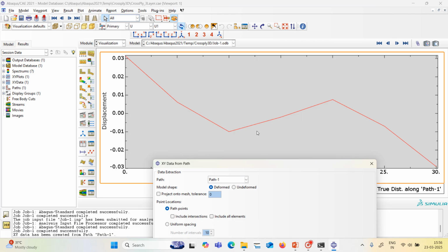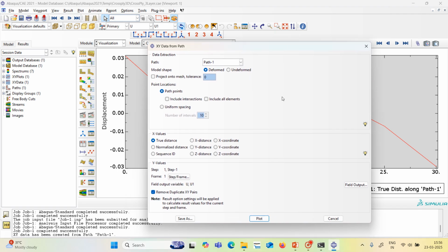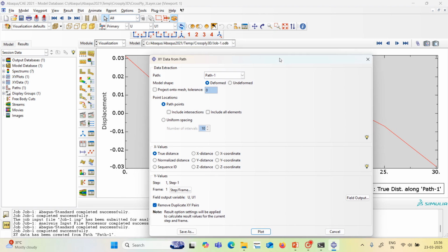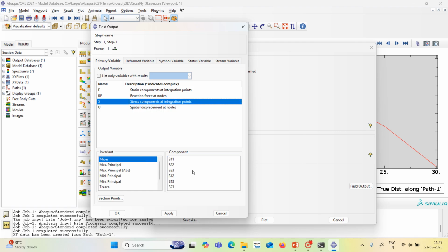Pagano's paper, but there we have seen that it is given for the sinusoidal distributed load, and also the mesh, to get those results accurate we have to mesh it very fine. But here we have done it for the uniformly distributed load. So we have to change the loading type and then we can compare with Pagano's load. But here we wanted to show that we are getting the warping of the in-plane displacement. Okay, this is ux, along the x direction. Similarly, if you want to find v, we have to choose a different point for those results.